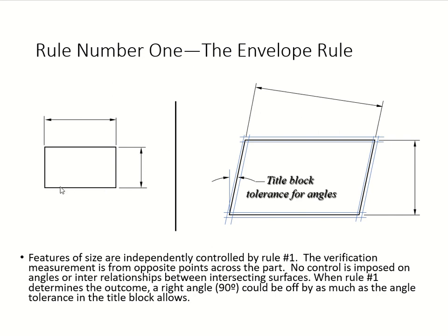But it seems to be dealing with a right angle. So you have to know where the tolerance is defined for this part or feature. You're going to take a look at your title block in your drawing. Down there in your title block, you're going to see the tolerance for angles, where the angle can vary, as long as it's around that 90 degrees plus or minus something. So it's telling you, if there isn't anything identified for the tolerance, go ahead and take a look at that title block.